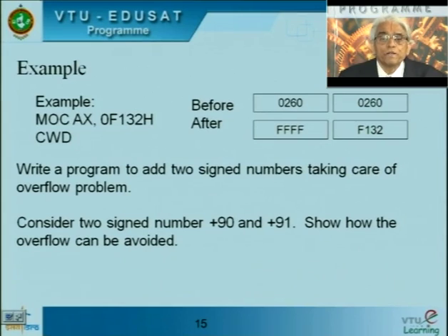It is only to differentiate between alphanumeric and numeric. We need to explicitly tell the assembler that it is a particular number. So the best option is, whenever you have A to F at the start of a number, prefix it with 0, so that 0F132 enables the assembler to understand that it is a number, not a variable.